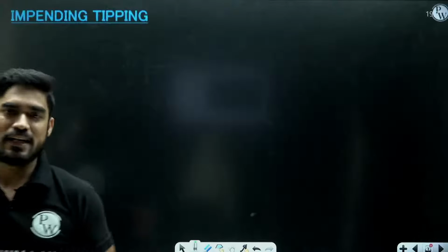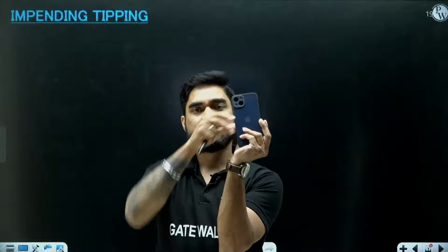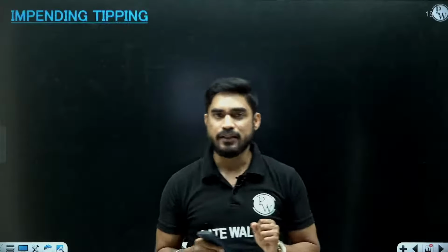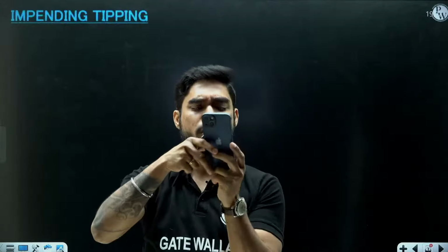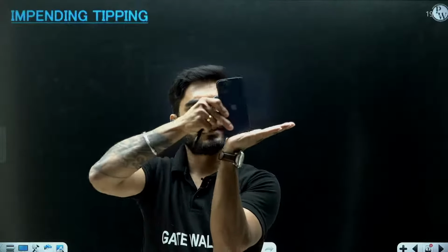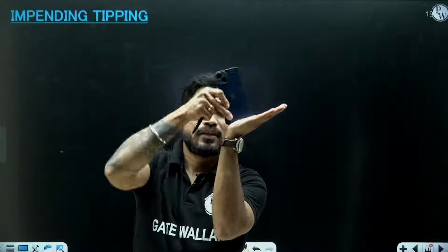Now, in order to understand tipping, I will take this example. Let's say this is a box, and it is resting on a horizontal floor and you are applying a force. Now, when this box will move, there can be two cases. Case number 1, this box can move by sliding. If I am applying a force in order to move this box, it might move like this. So this is known as sliding. And case number 2, this box can move like this, and this is known as tipping. So impending sliding or impending slipping, and impending tipping.